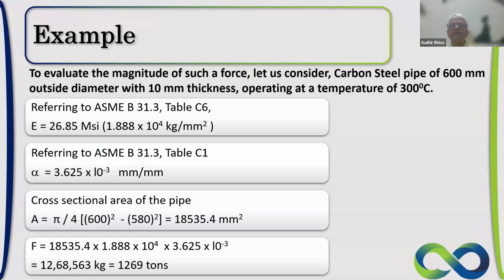It is going to generate a heavy amount of force. We have not even gone to the calculation of the stresses in the piping system, which may be really higher than expected from the code. So this simple equation tells us that stress analysis calculations are very much important for systems which are carrying fluids at a considerable temperature above the ambient temperature.